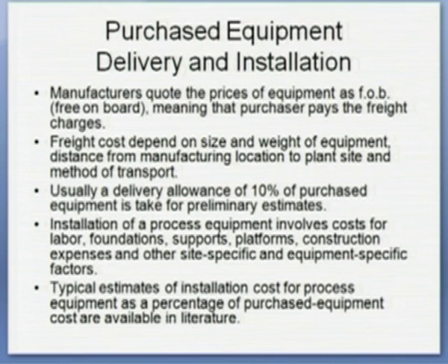Then the instrumentation and control, this is typically 8 to 50% depending on the type of equipment. The total cost varies, 8 to 50% of the total delivered equipment cost. Remember, it is not purchased but delivered cost, that includes the transportation. Then for a normal solid-fluid chemical processing plant, typically 26% of the delivered purchase equipment cost is recommended as the instrumentation and process control cost.